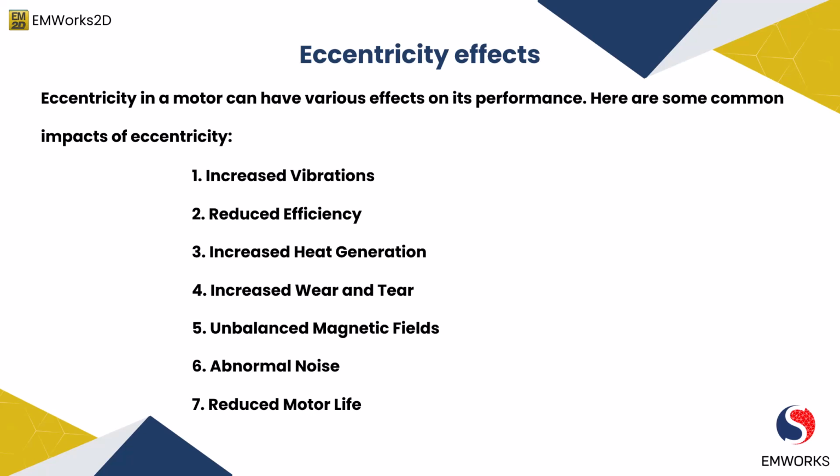Eccentricity can result in uneven contact and rubbing between the rotor and stator. This can lead to increased wear on motor components such as bearings, rotor bars, and stator winding. Over time, this wear and tear can cause further deterioration of the motor's performance and reliability.